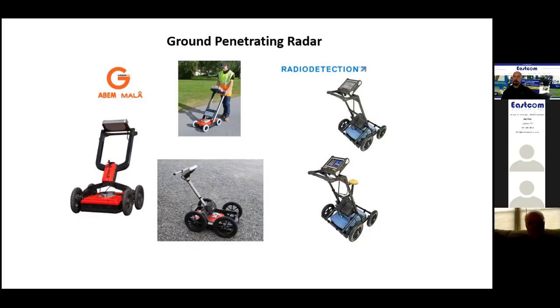Now, it's not for everybody, I'll admit that. It's not a yes or no tool. There's a little bit of thought process that has to go into it. You look at the screen and you say, okay, well, I think it's here. But it's a lot easier to use than most people think it is. So if you run into that situation where you have non-metallic utility line, no tracer wire, I highly recommend you take a look at ground penetrating radar.